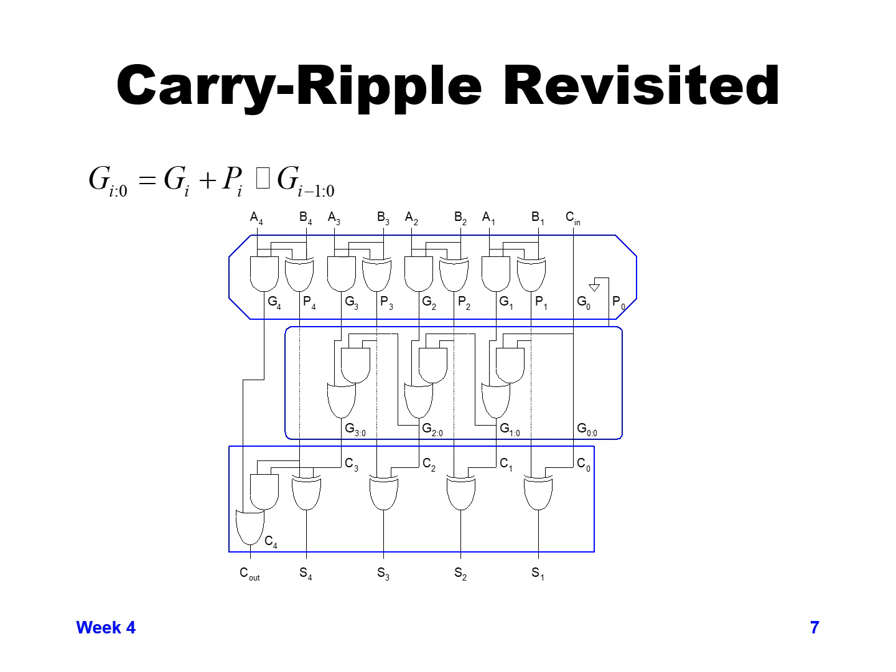And then likewise that goes into the next bit, and we just continue on there. You can see how our carry in, C in, goes into bit 1 to produce G1 colon 0, and then that ripples on to bit 2 to create G2 colon 0, and that ripples on to bit 3 to create G3 colon 0. This again is called a carry ripple function. It just ripples from bit to bit.